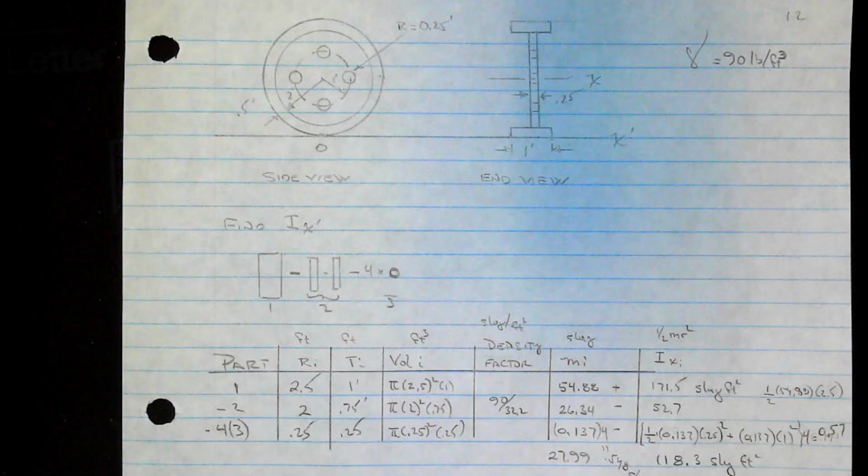We have mass 1, just multiply by 200, mass 2, mass 3. But masses 2 and 3, add another little negative sign here, are material cut away. So the total mass is this minus that, gives us 170.91 kilograms.